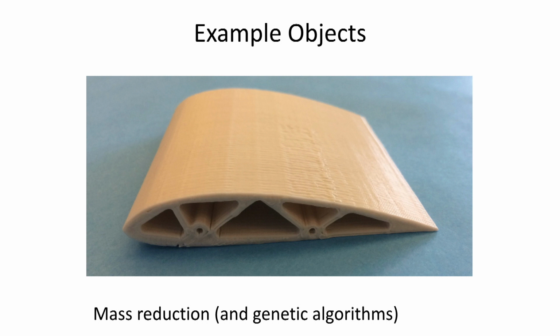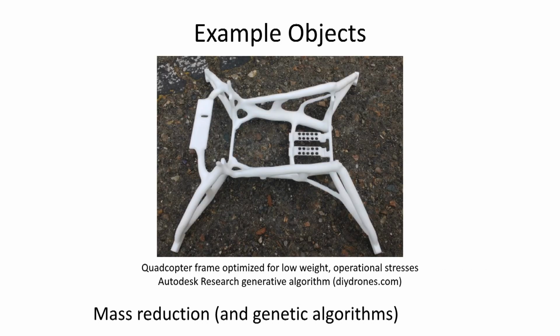So here we have a pretty simple kind of airfoil shape. And this is designed by a human. However, if you look up genetic algorithms or computer AI, iterative design, topology optimization, then you may find shapes like this that are even more complex and look a lot more organic as a result. Additive manufacturing is pretty much required in order to produce those parts because otherwise we can't leave that hollow space where we want with traditional manufacturing techniques.